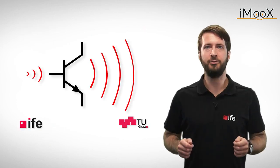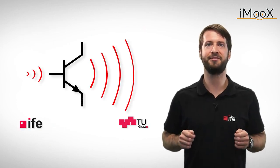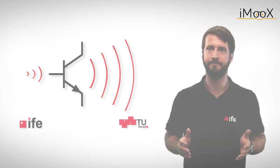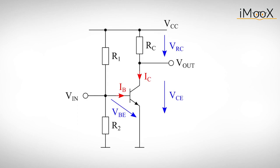Now let's explore the usefulness of these 3 graphs we just derived by considering the voltage amplifier circuit from before. For the sake of simplicity, we make the emitter resistor 0 ohms by connecting the emitter directly to ground. Now our output voltage is simply the collector emitter voltage VCE. We know that we can adjust a constant quiescent current IC by adjusting the biasing voltage VBE with the voltage divider at the input.